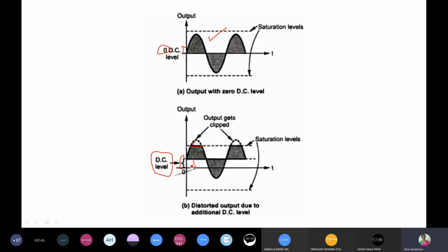What we are going to do is design some circuits using an emitter follower, that is, the common collector amplifier. Why have we chosen the emitter follower? Because the emitter follower gain is unity. Whatever input you give, the same output will be available at the output. So no further amplification or reduction of the signal takes place.